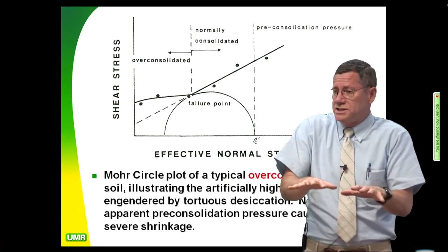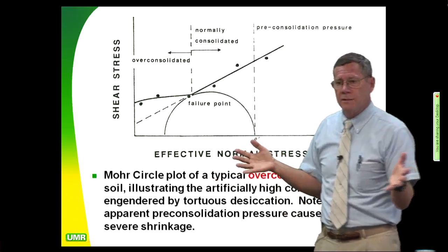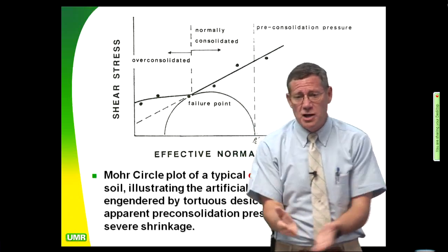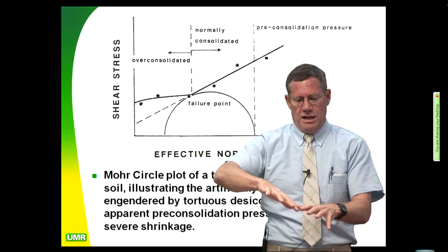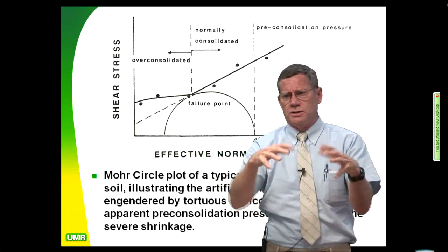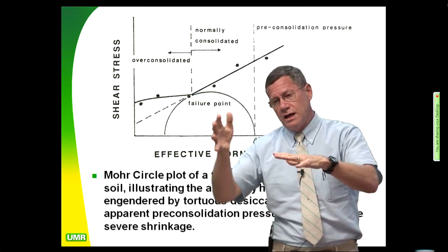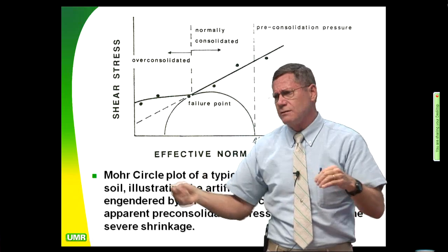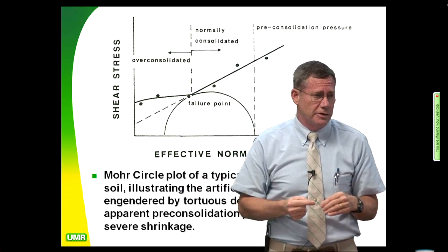And it's stabilized for the environmental conditions to which it's subjected today. And everything's fine till you make a cut in it. You go out there and make a cut, now you rapidly unload it in a couple hours, and all of a sudden it's going to heave, absorb moisture, and start moving around on you. And once it starts getting a slip surface, you can actually see 80% strength loss. That's scary. That's what happened in the Panama Canal with the Cucaracha Shale.